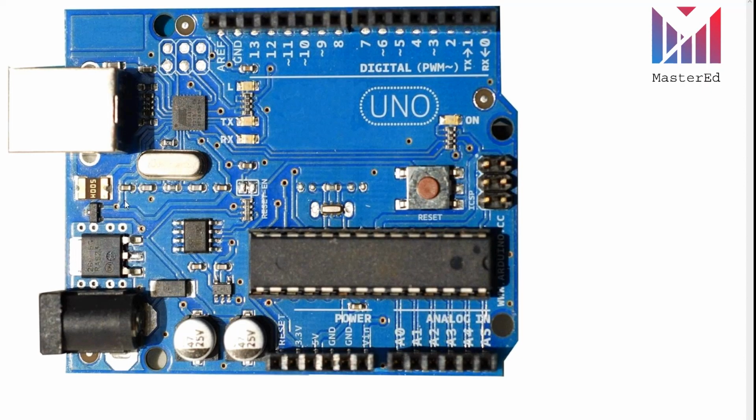Arduino board has physical pins. In particular, our Arduino Uno R3 board has 20 total amounts of pins. 14 of those pins are digital pins located right here, and other 6 are analog input pins. The 3rd, 5th, 6th, 9th, 10th, 11th of the digital pins are PWM pins. And the remaining pins are digital I/O pins. But we can use PWM pins as digital I/O pins, but you cannot do vice versa. Today we will only use digital pins.